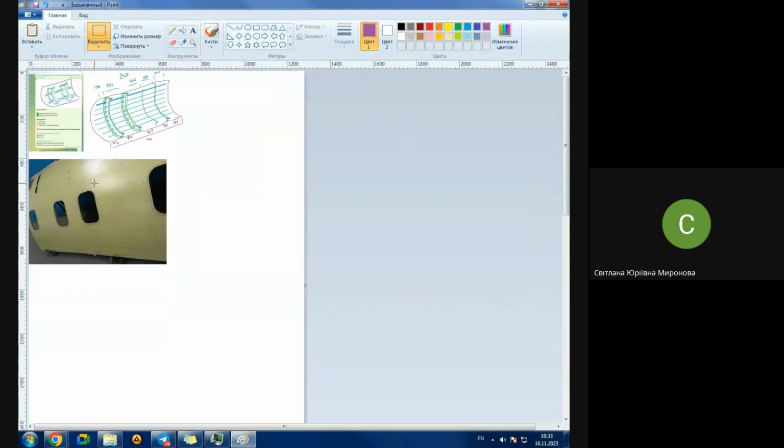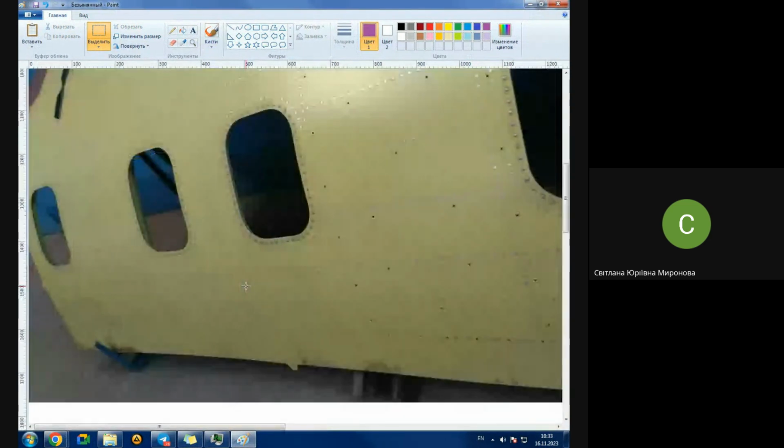Pay attention. Look, why do they have a double line of rivets here? Because it's a doubler plate here, between this stringer, double line of rivets, and this stringer, double line of rivets. There are unusual reinforced stringers here, and here is a doubling plate, and that is why it's not a regular place. Most regular for us is that one, for instance.